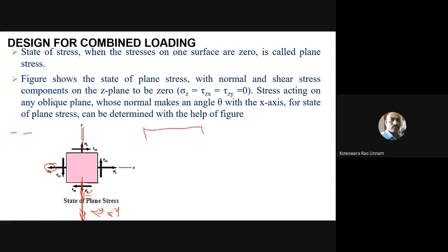Sometimes if I take this one, I'll say this load is a tensile load. We are taking this one as a positive load. But while solving problems, what you do is take the algebraic sum of the forces equal to 0. If the force is acting in this direction, we take it positive. If the force is acting like this, you take it negative. P minus P is equal to 0. That is the equilibrium equation, right? You are writing that.